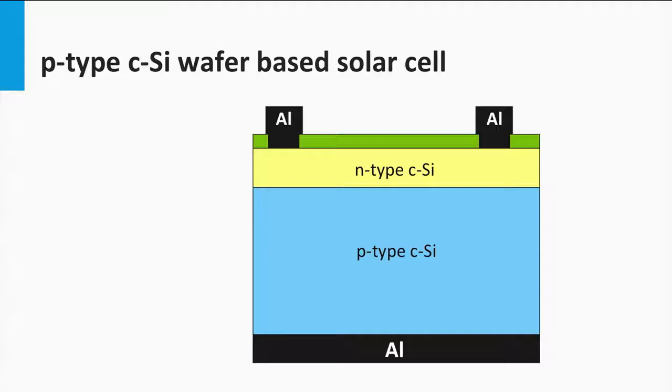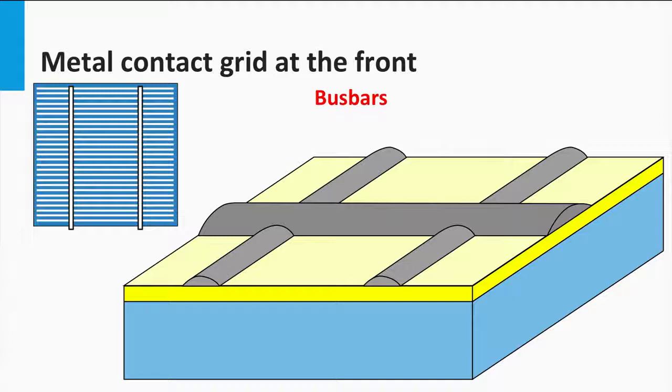In the figure, you see that the contact area between the metal and semiconductor is kept as small as possible. The sides of the metal contacts are buried in the insulating passivation layer. The area below the contact has been heavily doped. These two approaches reduce the recombination and collection losses at the metal contact.